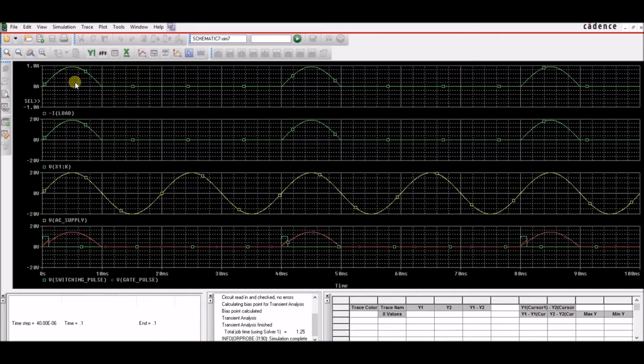Now voltage and the current gives you the power. Now we are reducing the power because we are skipping one cycle. Now if you start skipping 2, 3, 4, your power to the load is reduced, of course, with the power interrupted.